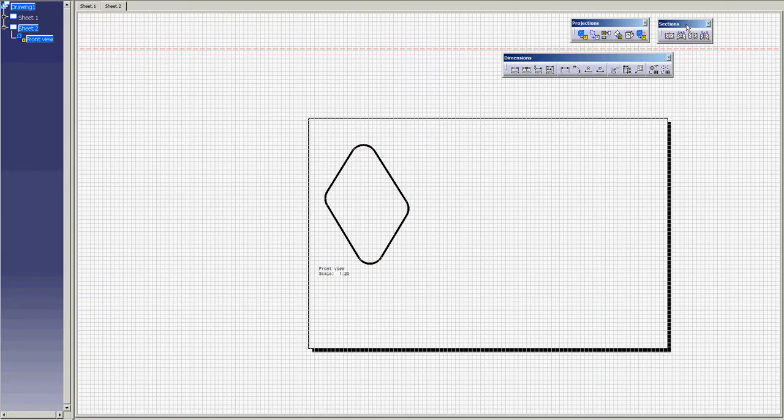So remember the section toolbar that we pulled off up here. Let's say we want to cut a section through one of these sides. Let's click the offset section view tool. Click it once, and I can draw a line across by clicking on the endpoints of that curve. But I want this to be perpendicular. So you can see before I click the second time, as I drag around, it'll snap when it's perpendicular to that curve. So I can go perpendicular to either the left portion of that section or the right portion of that section.